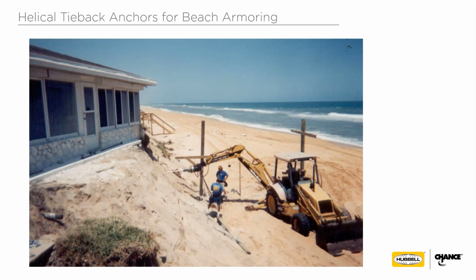So here, this is on the east coast of Florida after Hurricane Charlie. It's hard to believe, but they built shallow foundations in the sand dunes up until about the mid 80s in Florida. So the storm comes through, they're able to get on the beach with rubber tired equipment and install tiebacks underneath this structure where there's no room to put dead men or a drag wall in.